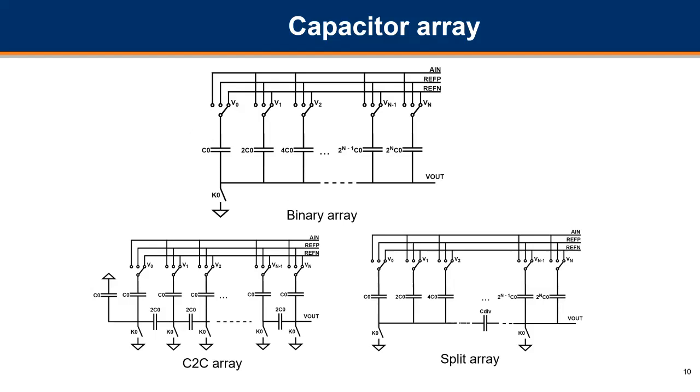The disadvantage is that with the large number of keys K0, different voltage values can be sampled in different sections because of jitter on the keys, which limits the maximum signal-to-noise ratio and the number of effective bits.